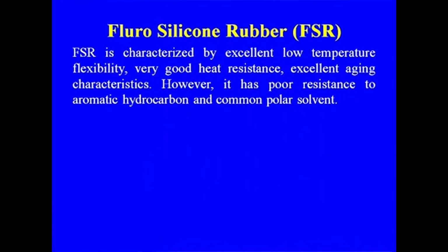Fluorosilicon rubber, this is another specialized rubber, is characterized by its excellent low temperature flexibility, very good heat resistance, excellent aging characteristics. However, it has poor resistance to aromatic hydrocarbons and common polar solvents. So, this is another class of the synthetic rubber.